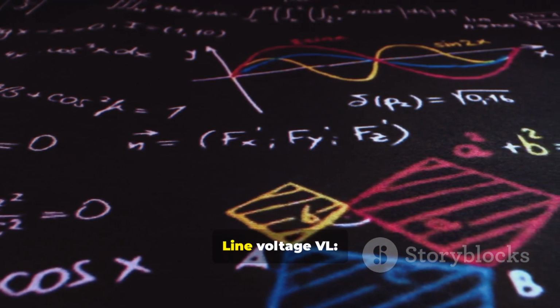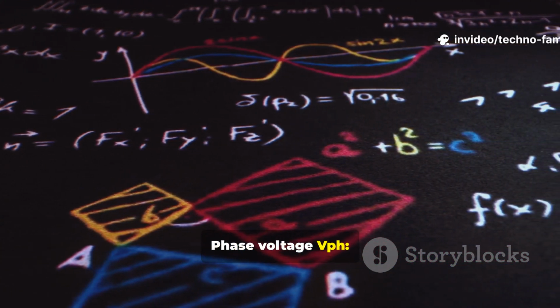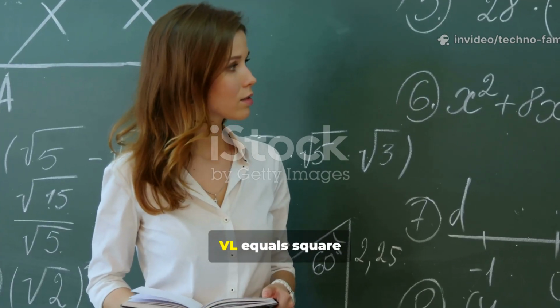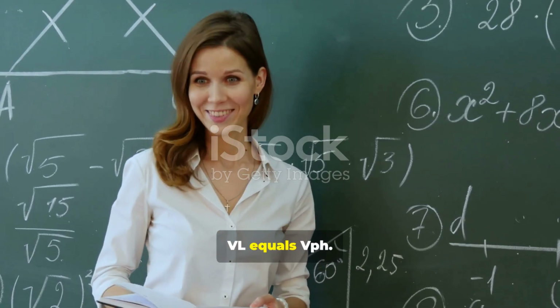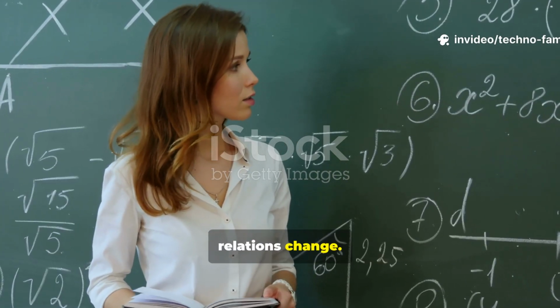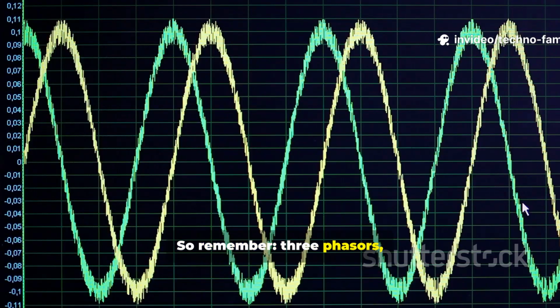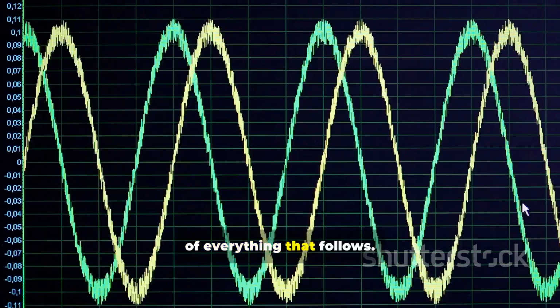Important terms: line voltage VL, measured between two lines; phase voltage VPH, measured between line and neutral. In star connection, VL equals square root of 3 times VPH. In delta, VL equals VPH. Similarly, line current and phase current relations change. We'll see that in detail shortly. So remember, three phasors, 120 degrees apart, is the foundation of everything that follows.